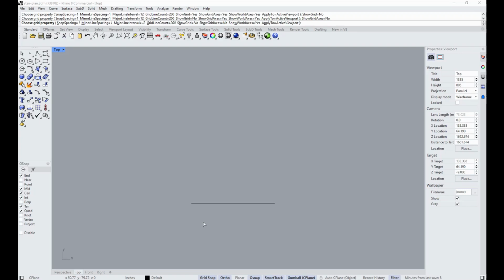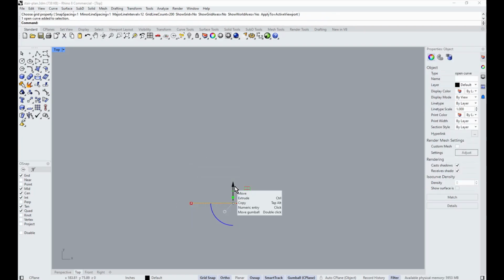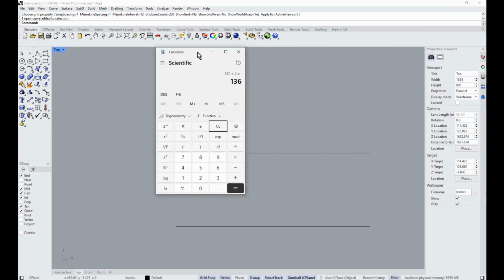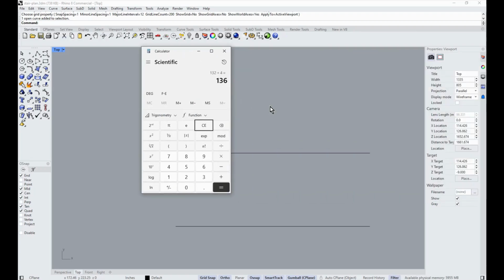So as brought up earlier, 11'4". We'll bring this up 136, which is 11'4". So this represents floor 1 versus floor 2. Now the next thing we have to check out is with 136, somewhere around 5.5 inches should be a good height. So you've got 136 as your total height. You divide it by, just try, 5.5.